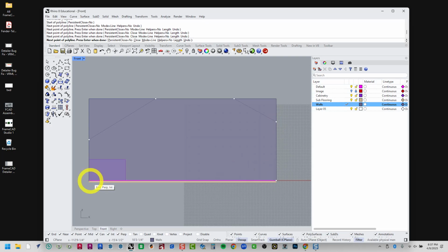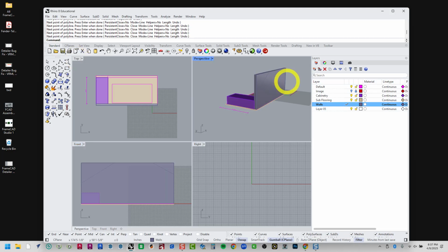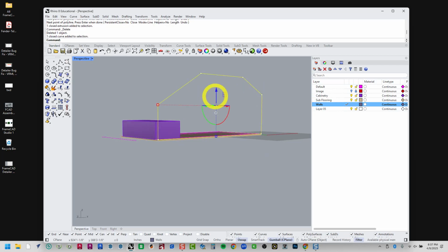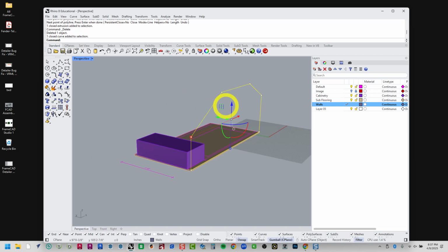Make sure you're selecting the right O-snaps, right? The right ends, the right near points, because it's very easy to draw that in front view, and actually when you get to perspective view, you have points way over there in the background, you have points up in the front, you have like this three-dimensional 2D curve, okay? And it looks kind of like this.